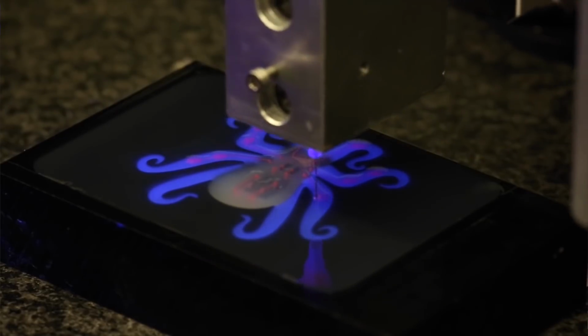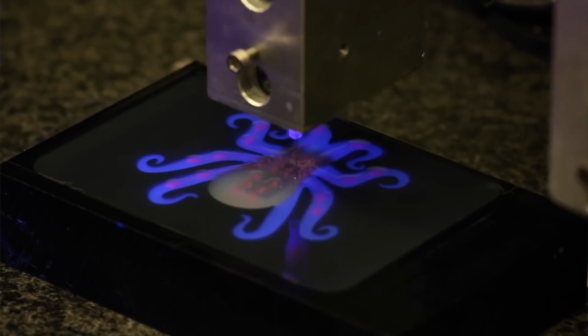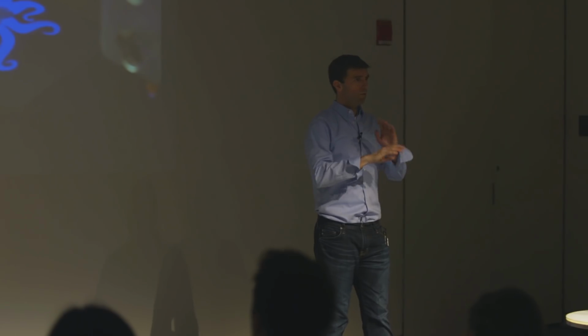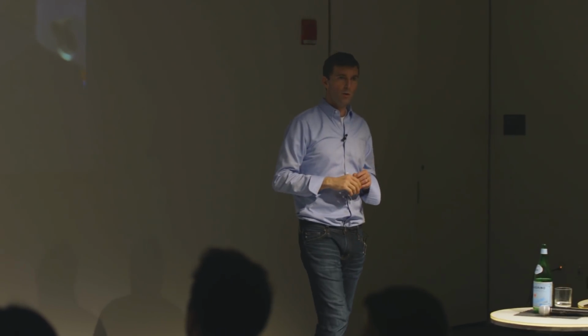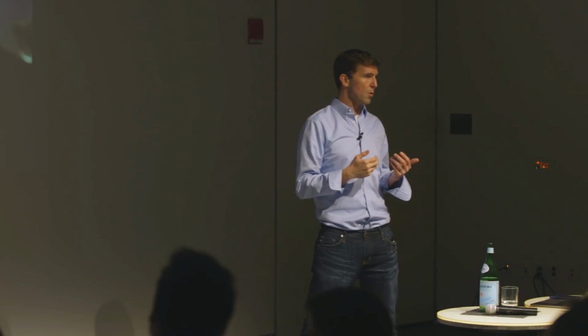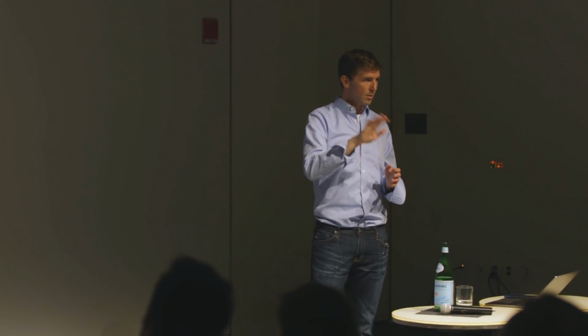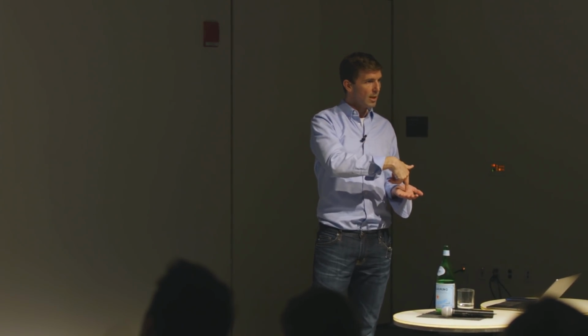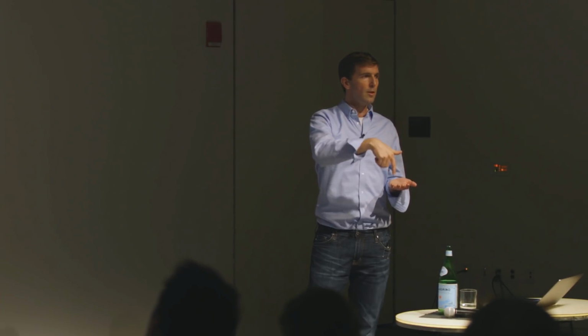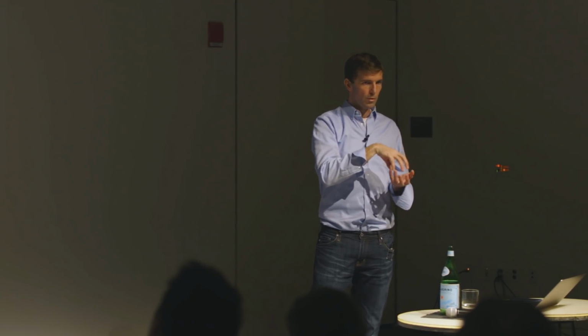And this uncured elastomer then is being injected with a sacrificial ink. And so there's all sorts of tricks that are associated with the rheology of this to get these to be stable structures even though uncured. But nonetheless, let's ignore that for a minute. They're able to inject this sacrificial ink wherever they want within the structure of this uncured elastomer. And this eventually forms the vasculature, if you will, of this robot.